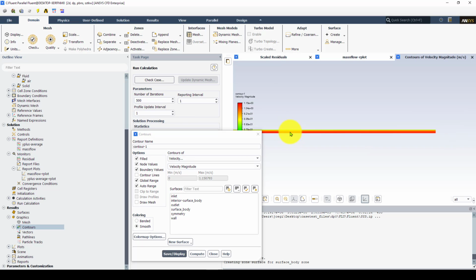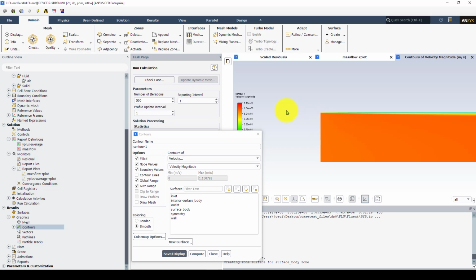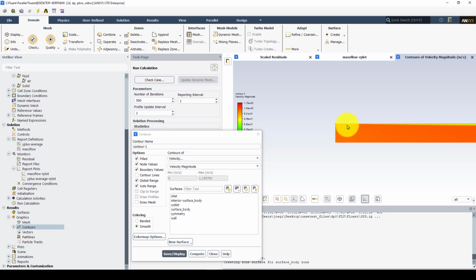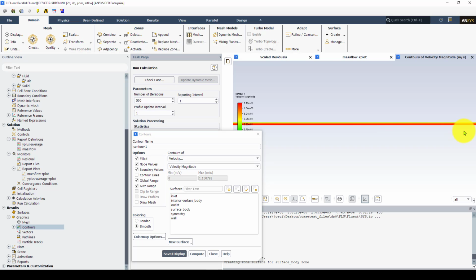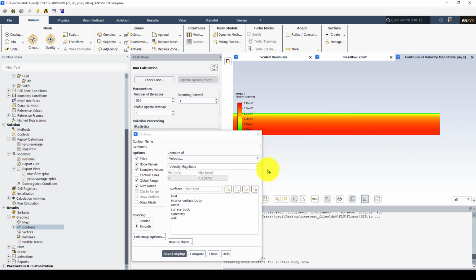I chose this distance 7 because here we have an entrance length. So the flow enters here, and you need to have a given length until the point that the flow is fully developed. Okay. So for instance, if you put your mesh up to this point, you see that it's not fully developed. So then just find those correlations, and you will see that the dimensions I chose for this domain are kind of twice the maximum value, or the point where you have the fully developed flow.